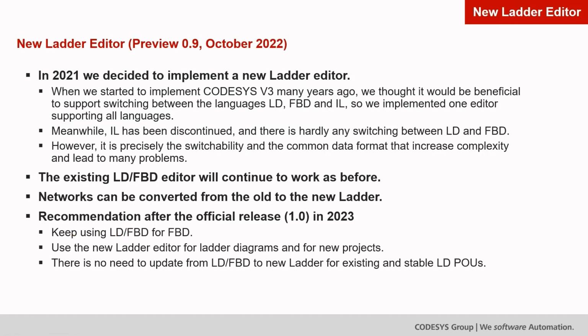Let's move on to the new implementation of the ladder editor. When we started to develop CODESYS many years ago, we combined the three programming languages, ladder, FBD, and instruction list into one editor. The possibility to switch between the languages seemed to be a big advantage for the user. In the meantime, however, instruction list no longer exists, and as far as we know, the programming language is rarely switched between ladder and FBD, especially in fully developed networks.